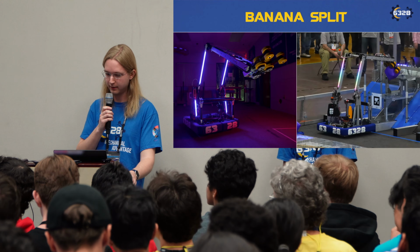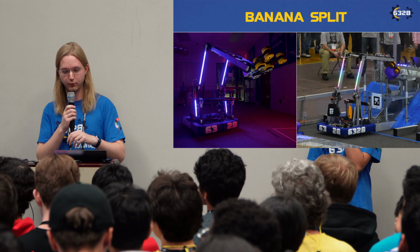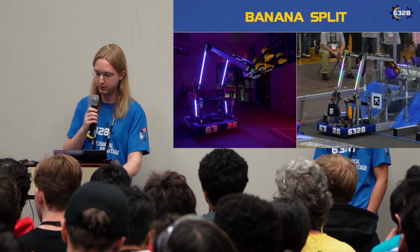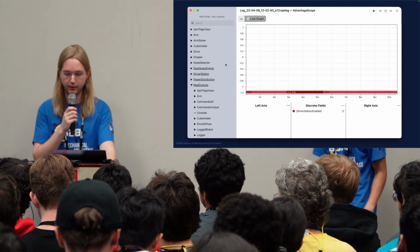It's called Banana Split. You can see it consists of a triple jointed arm, so there's a shoulder, elbow, and wrist. All of those arm joints are controlled by a feed-forward model and a PID controller, and of course those all need to be tuned. So let's take a look at how we can analyze that arm behavior in AdvantageScope.